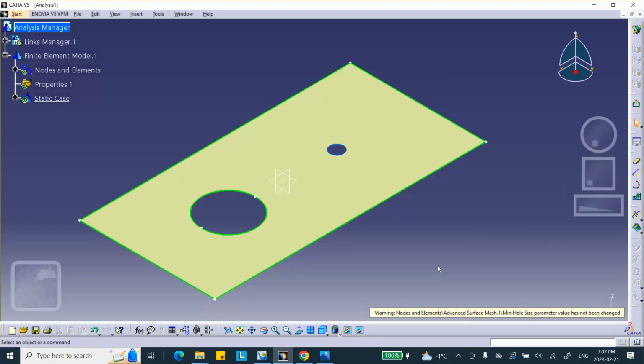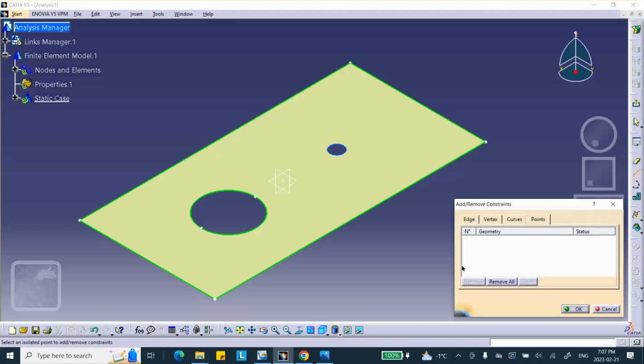You say, okay, there are a couple of things you want to do. If you click, for example, on this icon, see this icon right there? You click on it. We want to add a point as a constraint. So click on the point tab and go and select this point. In other words, include this as one of my meshed nodes. Later on, I want to put a force here, for example. That's one option. And what else do we have?